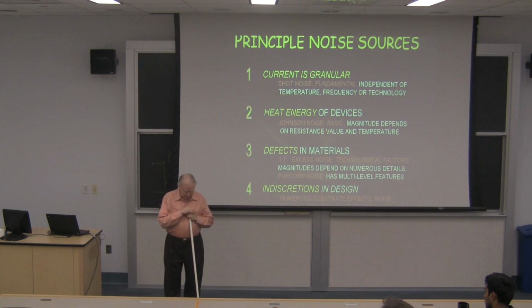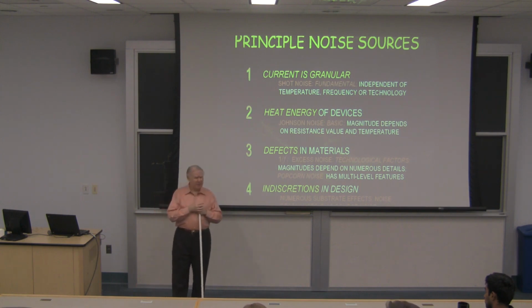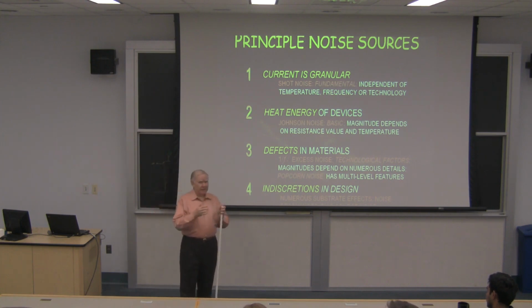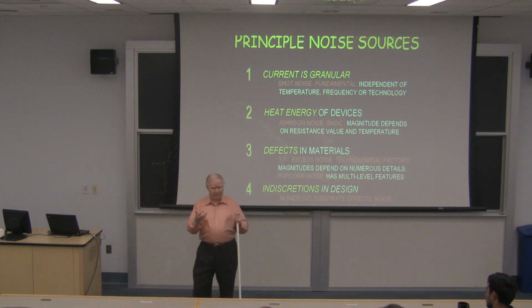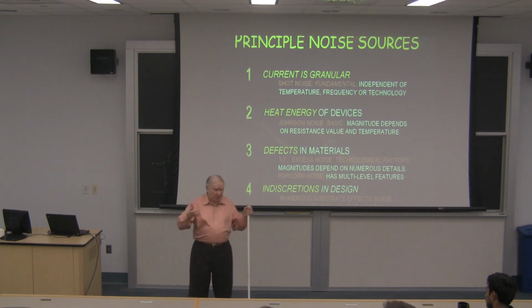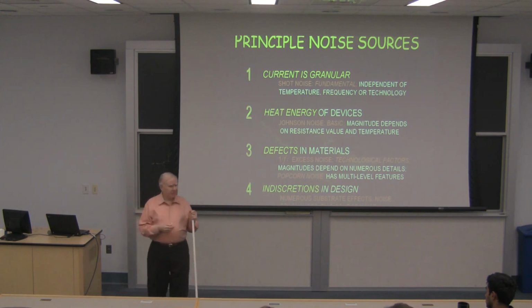But if you're too hasty about that, and you don't spend as much attention on that bias cell as on everything else, you may be in for a shock, because transistors don't know what they're supposed to do. They're mischievous little devils, you know. For example, if you design a cell phone receiver and you stick on a headphone driver, that's audio. Well, then when you start measuring the circuit, you find you have a 10 gigahertz oscillator.